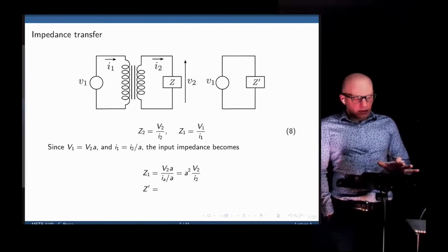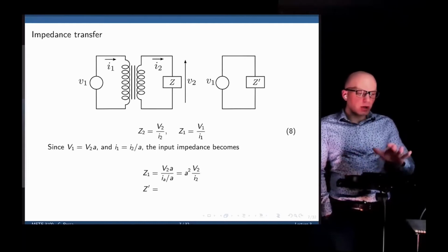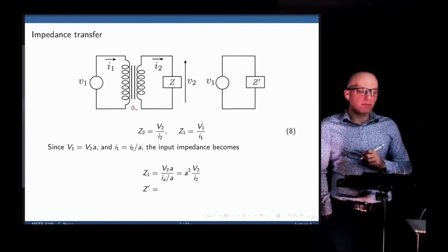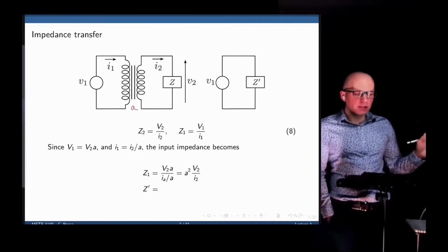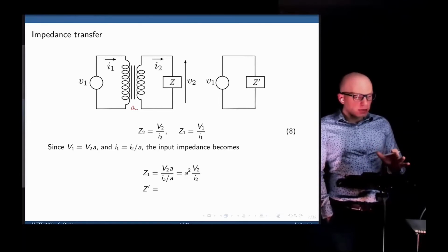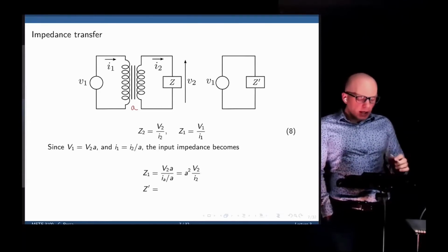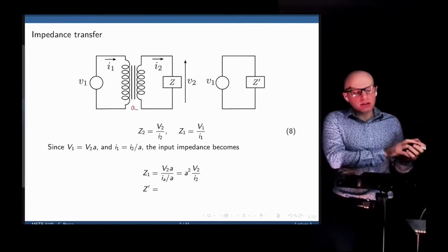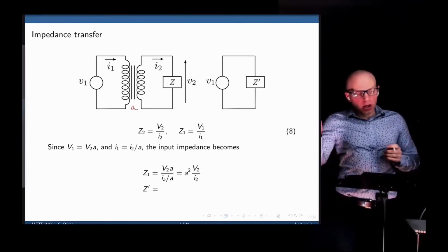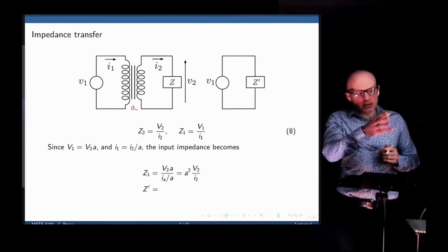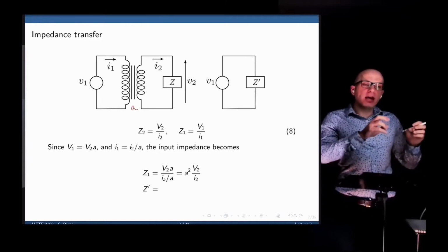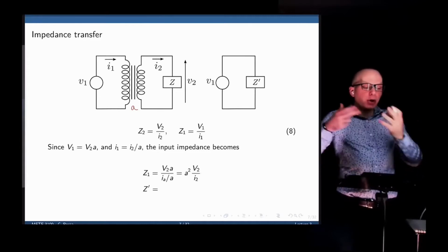In this simple scenario, we have an input voltage, the transformer with a turn ratio of A, and the output impedance Z. This makes the analysis a bit complicated. But knowing that if we connect this impedance in the output, that impedance takes power from the input, the source sees that impedance in the secondary winding as having an equivalent impedance in the primary winding.